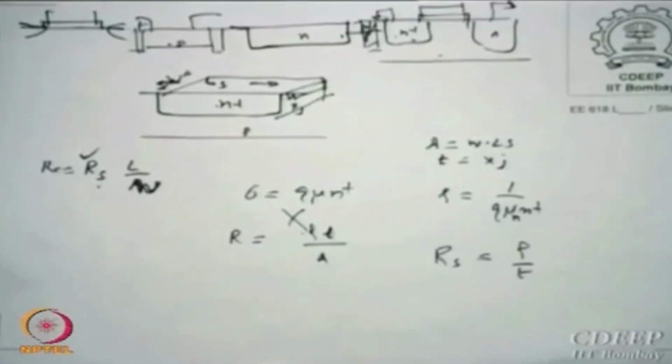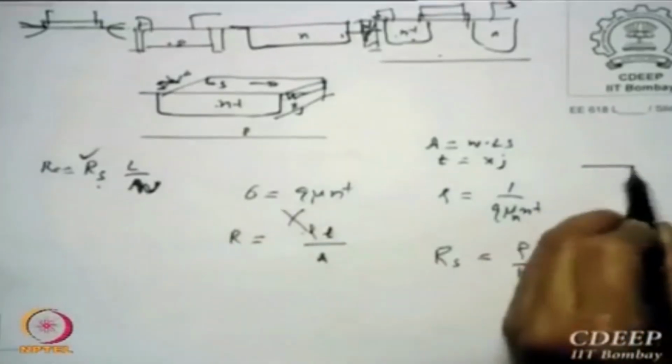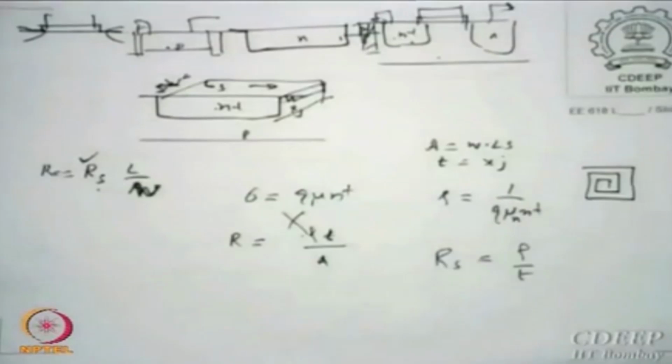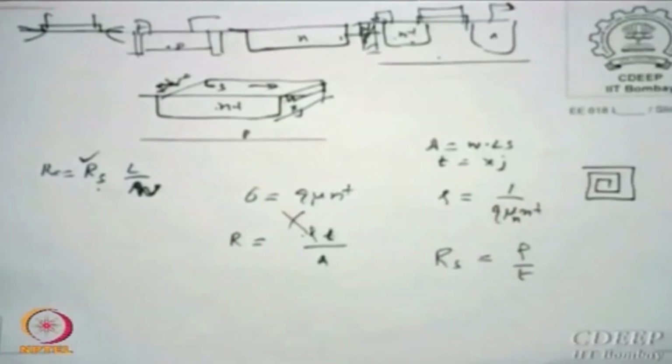What I cannot do then? Resistor I did, capacitor I did, diode I did, inductance. Inductance is nothing I can do about. All that I can do is print a spiral on top of this, and that is a very difficult game. It takes so much area; to make a small inductance, 0.1 nanohenry will still require some 20 or 18 turns.